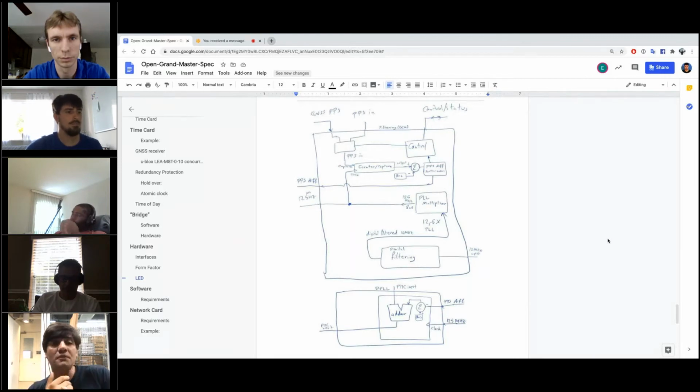Yeah. That's not enough, no problem. We put a DAC, let's say a 14 bit DAC, that feeds a VCO. The VCO feeds in now your beat, and now you have like 16,000 steps basically that you can adjust your beat, which is again 8 nanoseconds. And we're sticking to 8 nanoseconds because this is basically what is used more in standards. Also for the clock input for the FPGA, we're open to anything else.